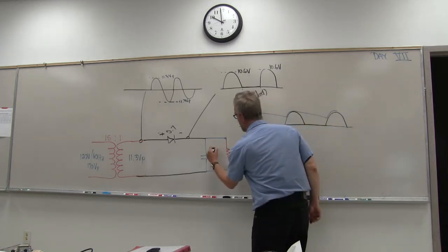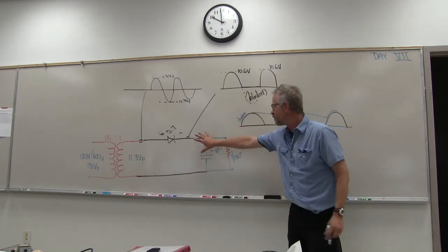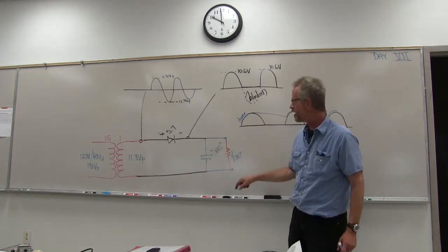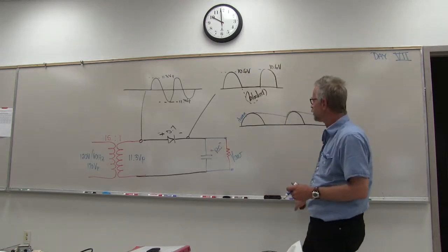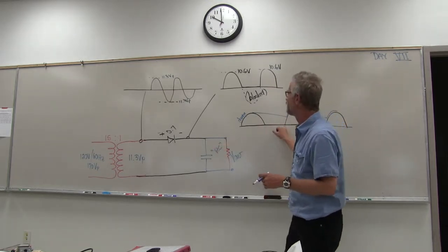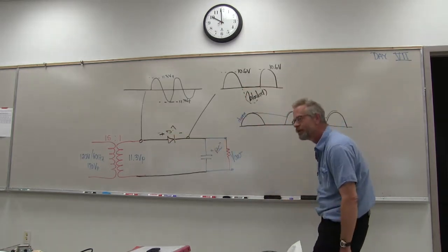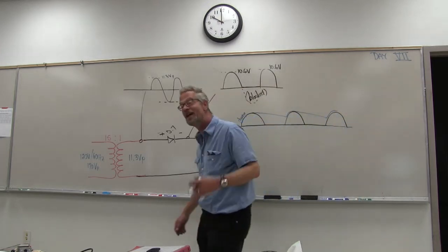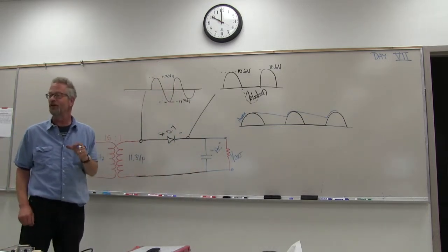Okay, you have an RC time constant. The capacitor charges up from the source, and once the source goes away, it discharges through the resistor. And as it discharges, of course, it loses some of its voltage. After a certain amount of time, it gets another issue of power from the source, charges back up, and then discharges. Perks back up and then discharges. It never gets down to zero because it doesn't discharge fast enough to get down to zero before it gets another.